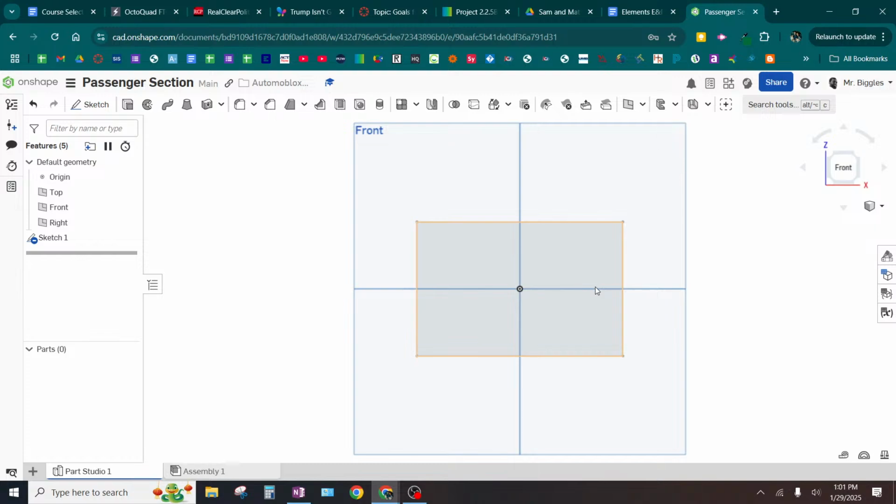So my recommendation is, when you're doing your measurements, I would not go to the hundredth of a millimeter. I would go to the tenth or even a whole millimeter for these larger things. For smaller things, maybe going to a tenth of a millimeter makes sense. But for these bigger dimensions, I would not get caught up in a tenth of a millimeter.